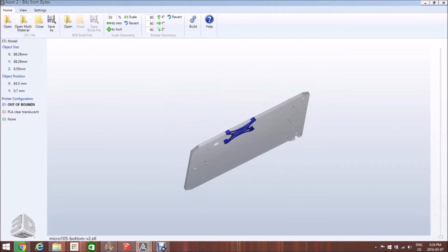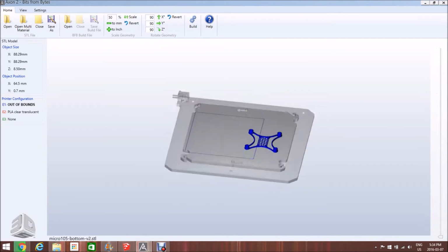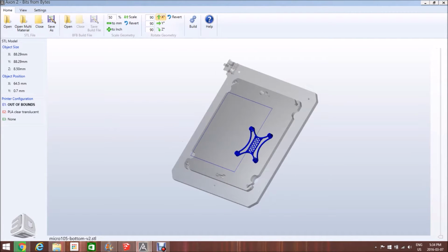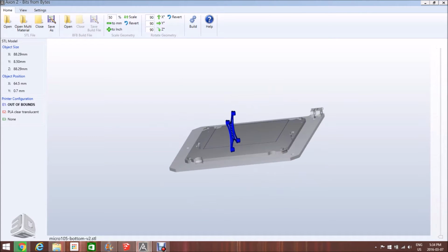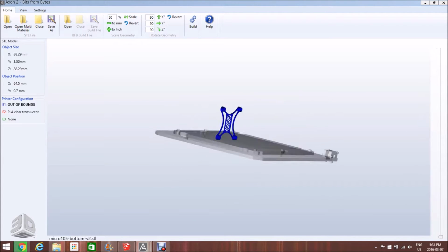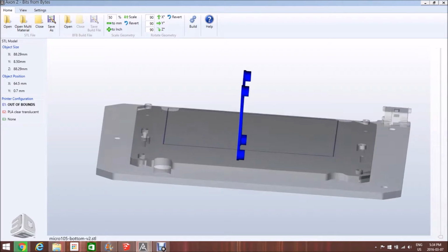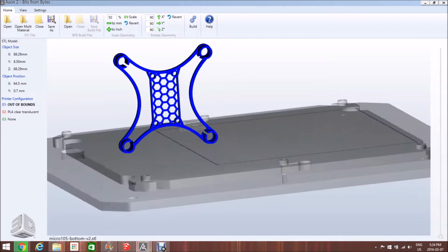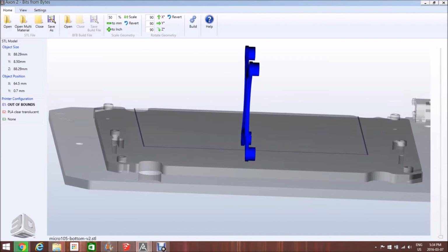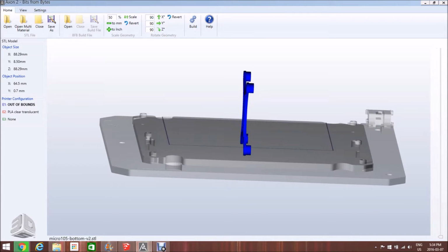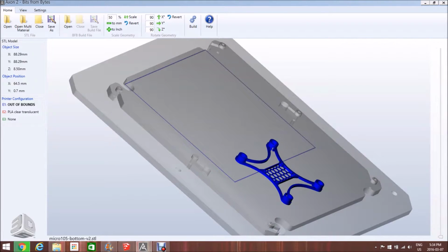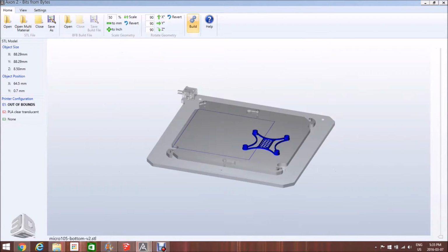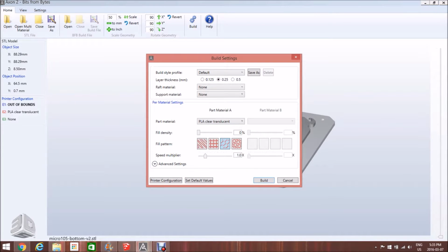So we can move it off to one side depending on what kind of extrusions we're using. We can also change the orientation. Why does this matter? Well, in some orientations, the part may not be very strong or it may not be printable, such as this orientation here. This is not very printable, nor would the completed object be very strong. In this case, we'd want it to lay down flat, quite like this.